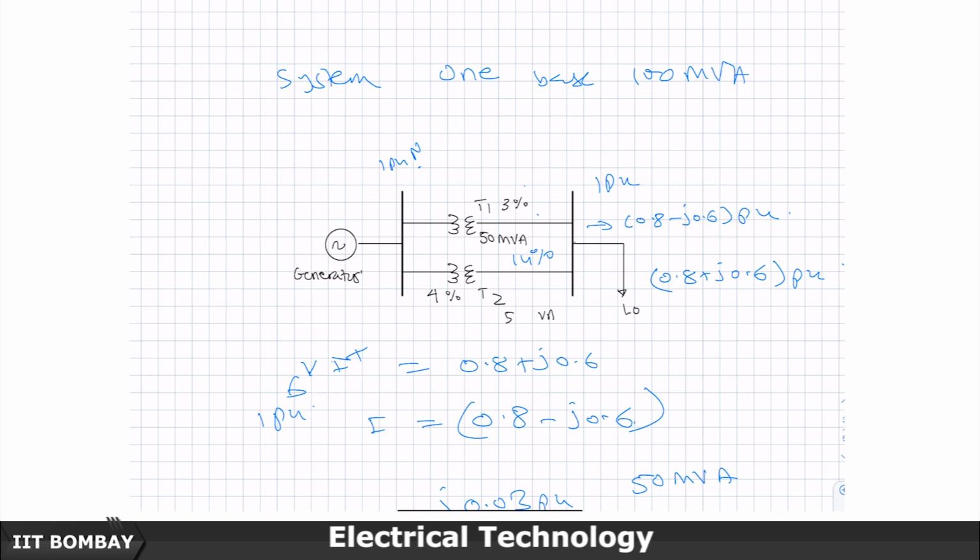So parallel operation of transformers should either have properly identical impedances, or we use transformer taps to alter the voltage levels, putting this in a boost mode to reduce this current here.